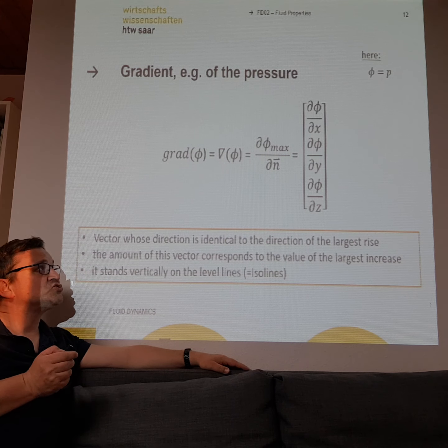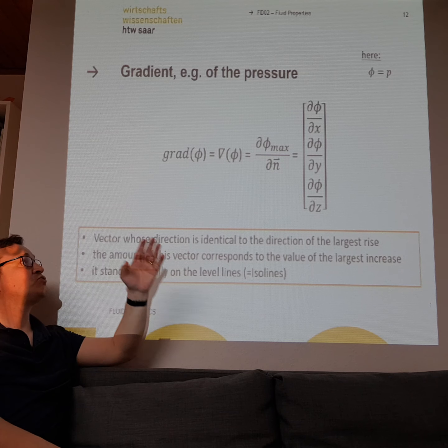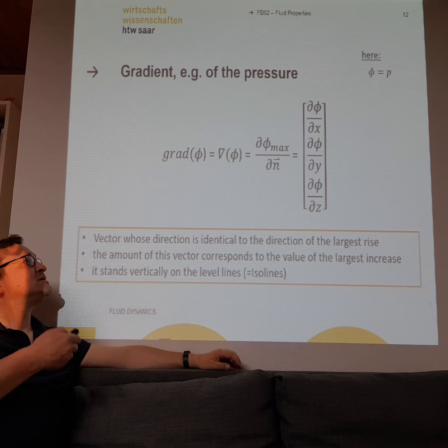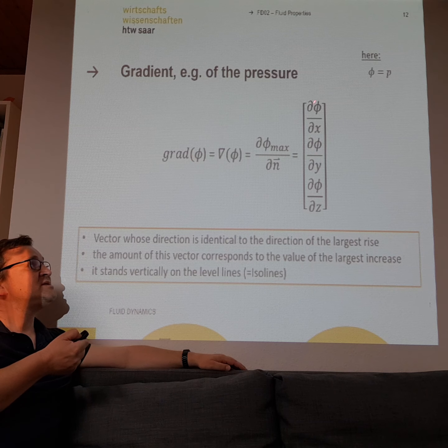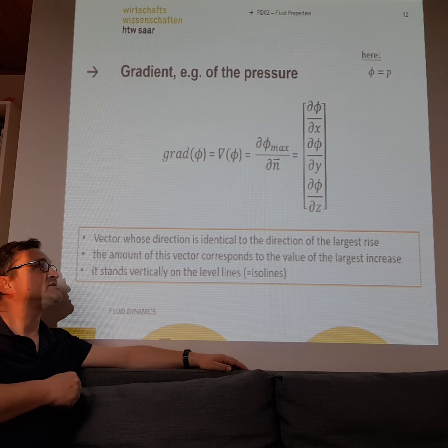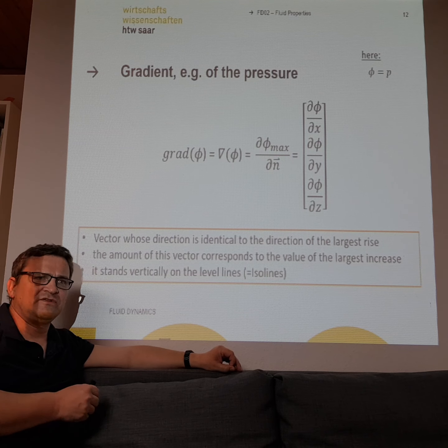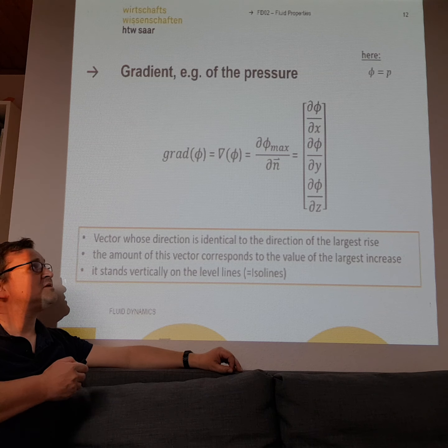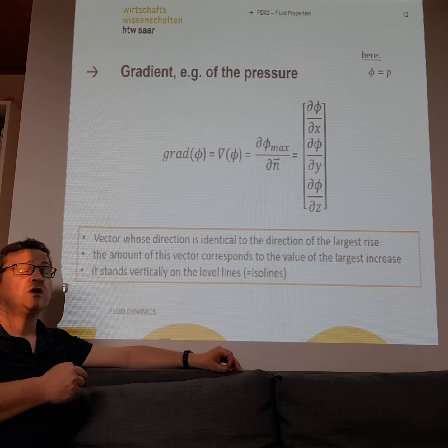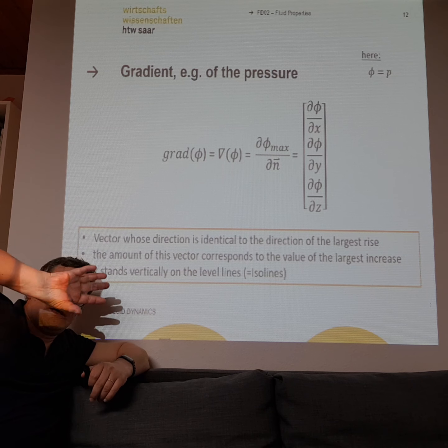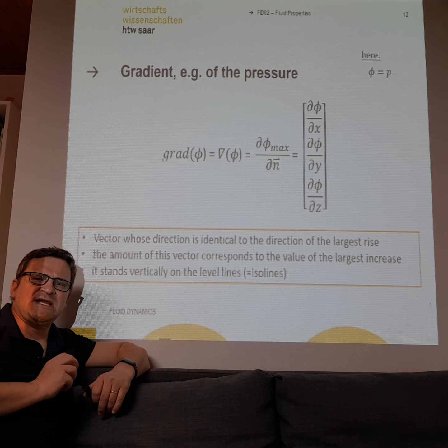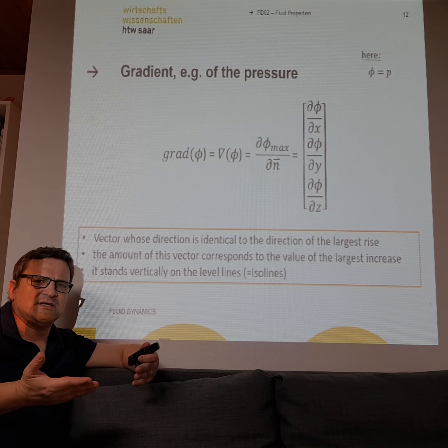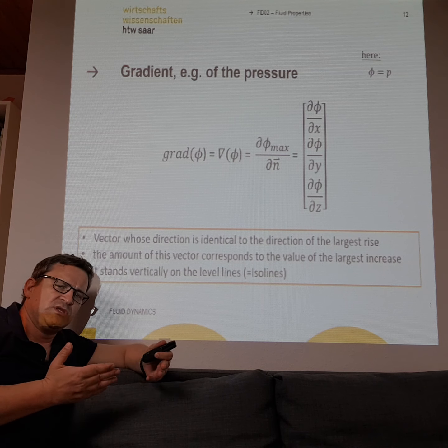If we solve all these, we call this the gradient. Grad phi, you will often see this. It's easy to write, but it means a lot. Gradient phi means the derivative in every direction of the mesh. And in computational fluid dynamics, there's a famous symbol called the nabla operator. Nabla looks a bit like a rotated, upside-down delta. Everyone knows what delta is: a difference between two positions.